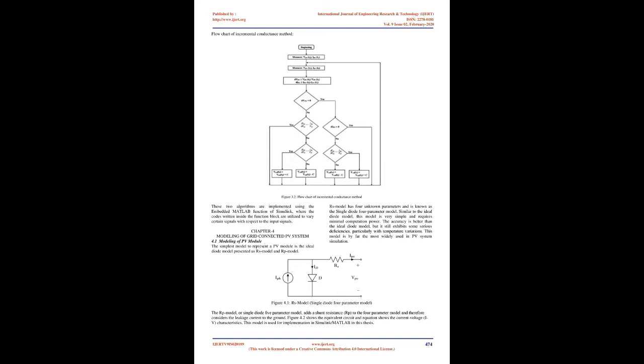2.3.2 Impact of solar radiation on the VI characteristic curve of a photovoltaic module. Standard sunlight conditions on a clear day are assumed to be 1000 watts of solar energy per square meter, 1000 W/m2. This is sometimes called one sun, or a peak sun. Less than one sun will reduce the current output of the module by a proportional amount. For example, if only half sun, 500 W/m2, is available, the amount of output current is roughly cut in half.